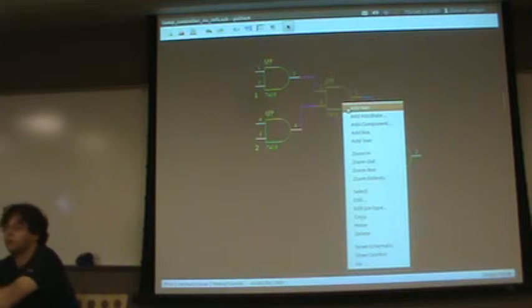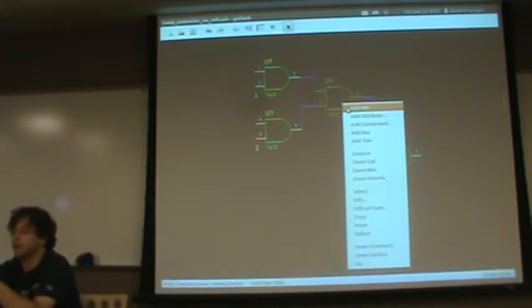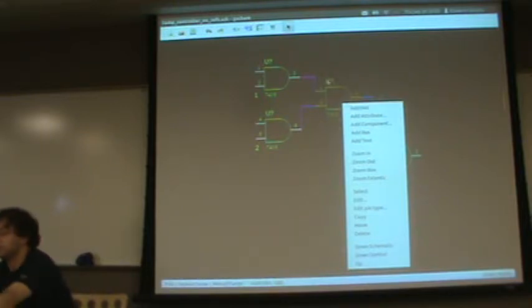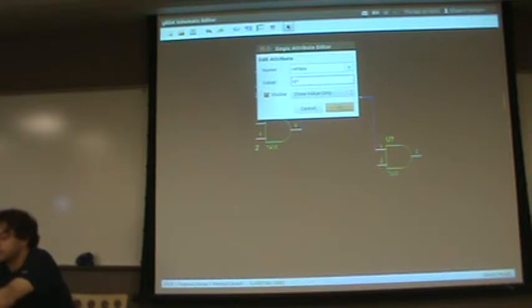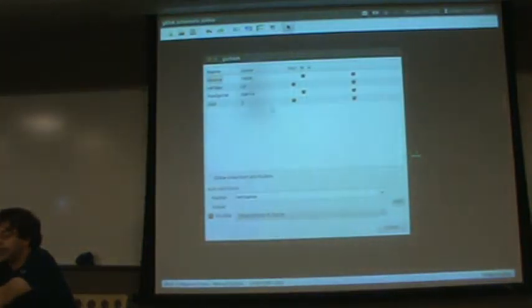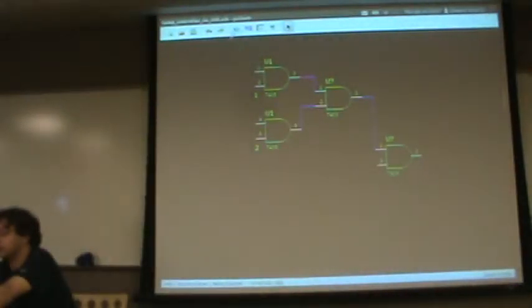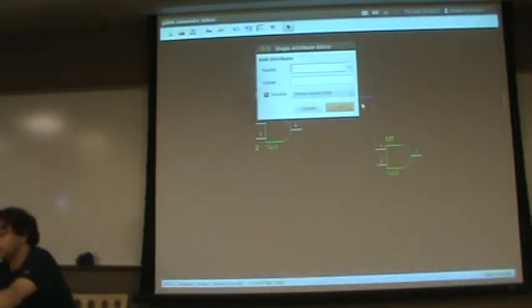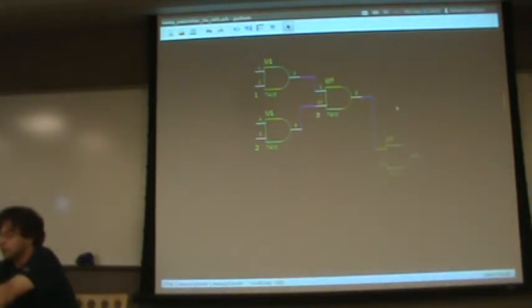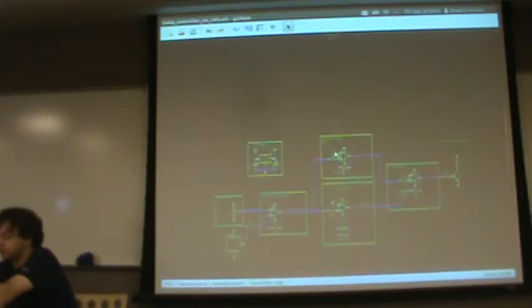And also, if I wanted to design a PCB, I can import the schematic into PCB, and it will know that these are all the same chip. If I set the reference designator, I'm going to do the same. So if I made this U1, U1. So now what I've done is I've said that these 2 are actually part of the same chip. And I can continue doing that up to slot 4 on this. So that's slotting.